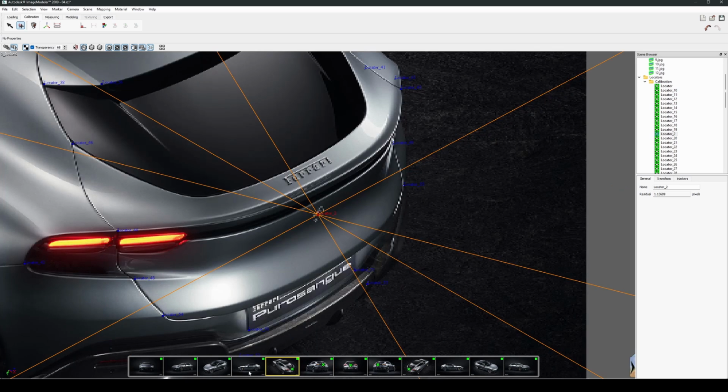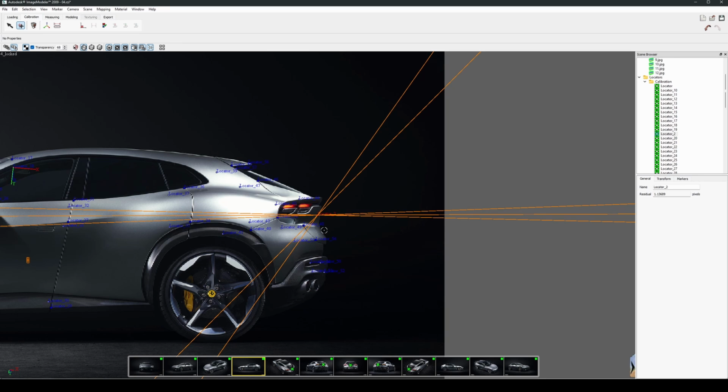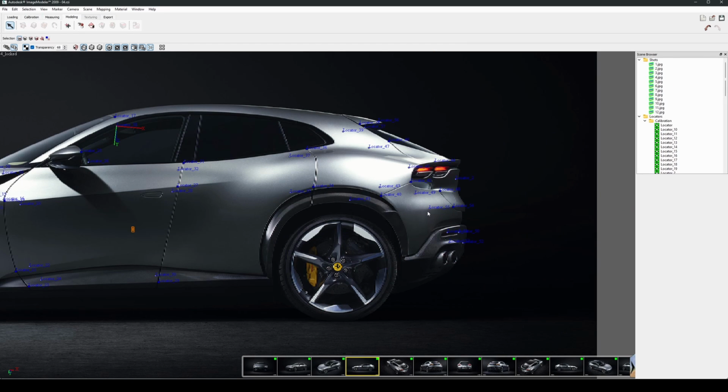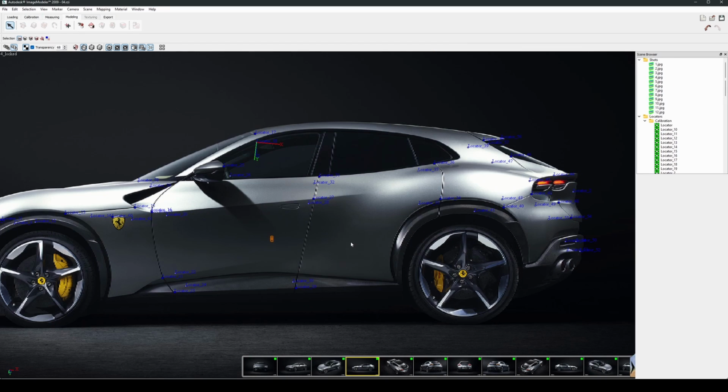That implies a good calibration, and you are good to go. So with the calibration done, the next thing we're going to do is to define the axes of this scene we have here. So we're going to head over into the calibrations tab here, and then here where it says define world space, we're going to left click on that to add in an axis icon here. We're going to use this to define the axes of this scene.